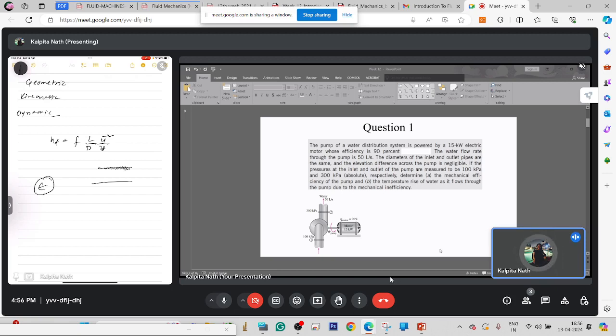Epsilon, that is the height of these perturbations, is important because the velocity is very high. So these perturbations will be affecting the fluid flow, right? In laminar flow, the perturbations are not allowed to grow, and whatever disturbances are created by the wall get damped out almost instantaneously. Thus the effect of wall disturbance is not important in case of laminar flow. But in case of turbulent flow, the surface roughness is important, right? So in case of turbulent flow, what is happening?